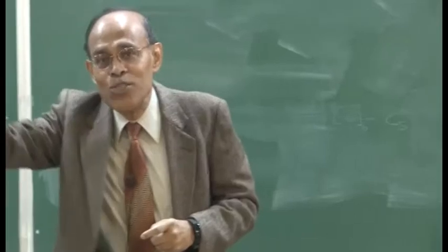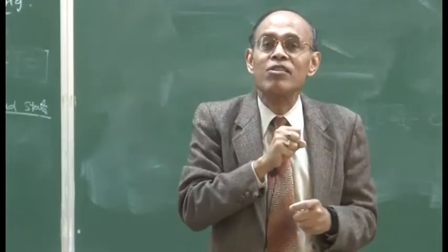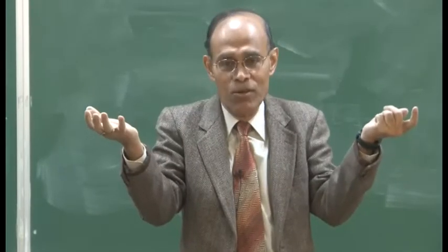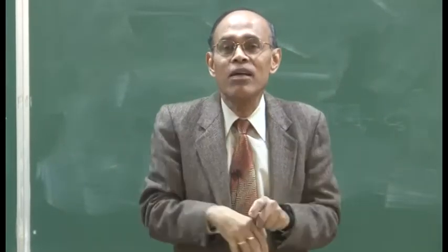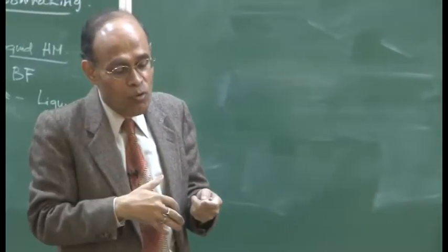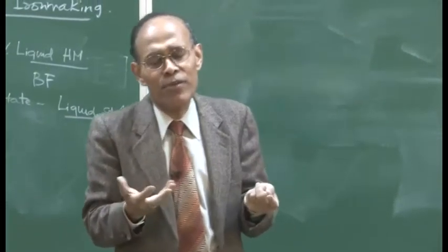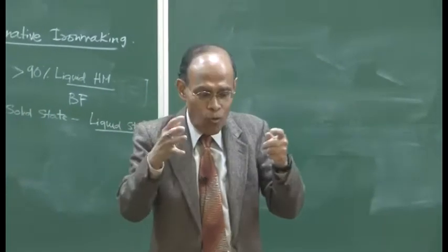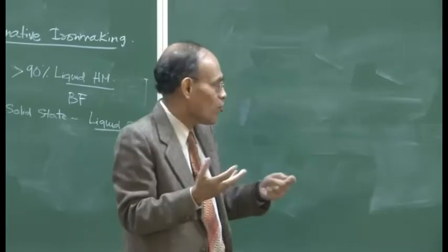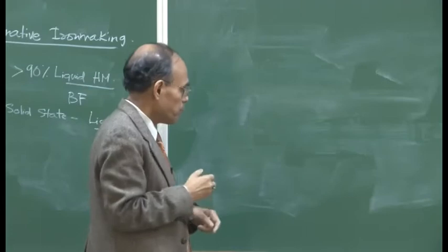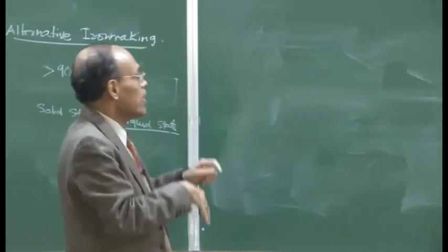So, we buy coke from Australia, we buy coke from South Africa, blend them together with Indian coke, and if we blend them with 1:1 weight fractions, Indian coke which contains 25% ash and imported coke with 7 to 8% ash will give us a coke which will be about 13-14% or even 11% ash, which will be significantly better than using the Indian coke alone.